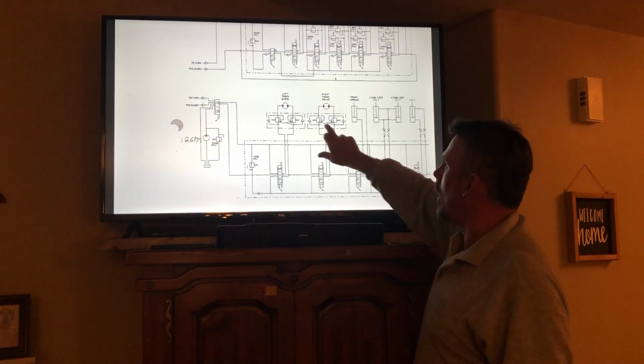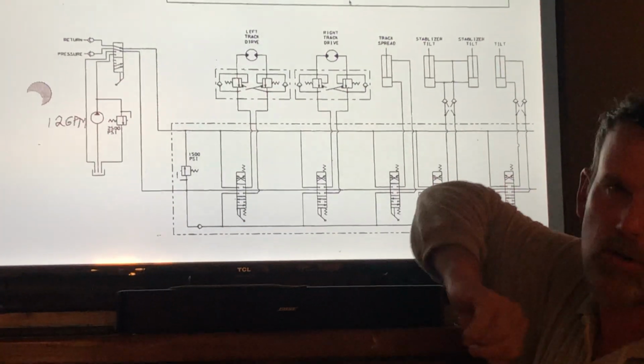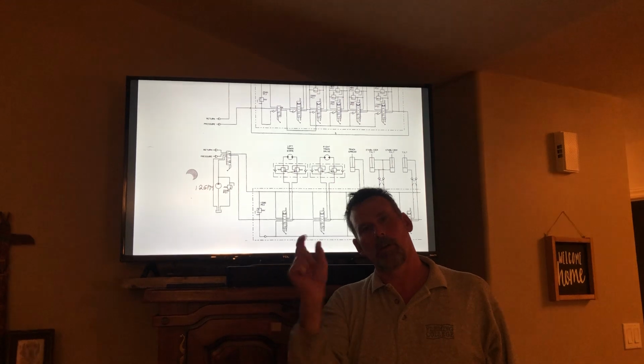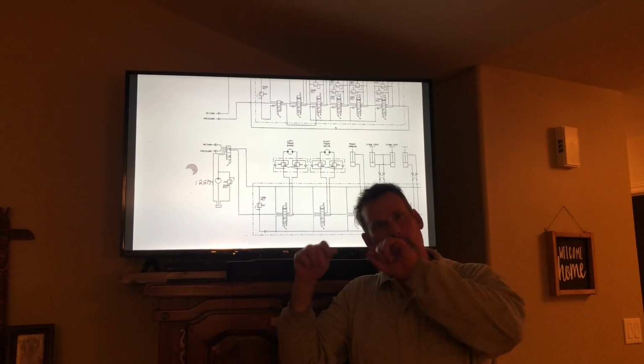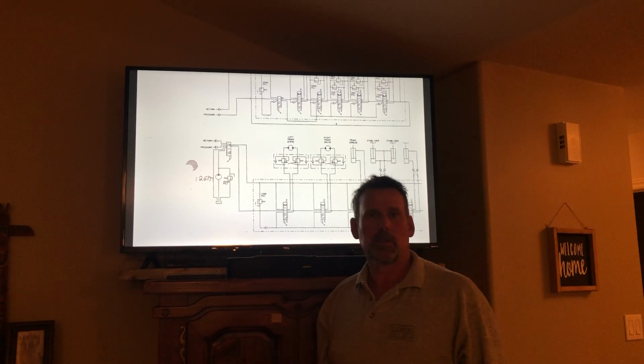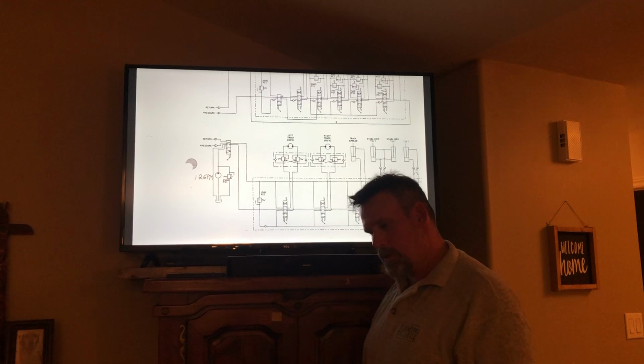It's just working off pilot signals, and this is bolted right onto the side of the track motor, and usually it's only about 4 inches long, and it has a little spool through it, and it has spring tension on each end so you can adjust it. It's a very simple system, but very effective. All right, so that's question 7.